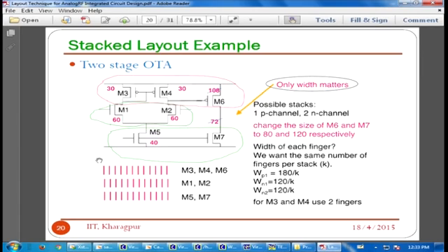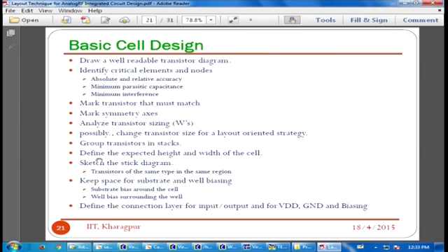So basically, two important aspects. One is the variation of the oxide thickness or variation of its doping parameter, which introduces changes in the transistors, and that is the spatial variation because of this. Now you plan your floorplan in such a way that these deviations will be cancelled. So if one has increased, one has decreased, you should not add them together, then the difference will be high. You should make it in such a way that their difference gets reduced. That is the whole philosophy of the floorplan.